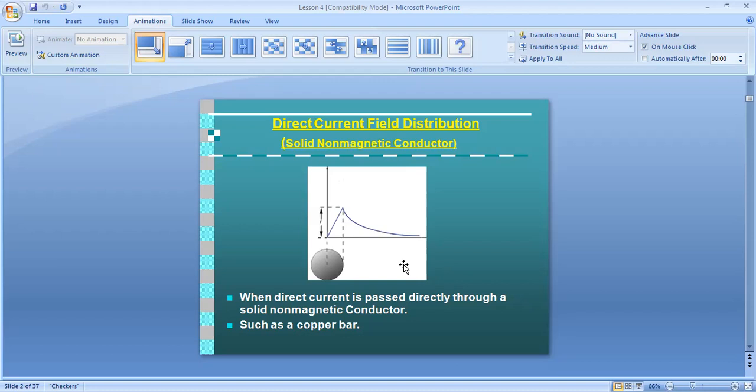That's why the field is reducing there. So the magnetic field depends upon the medium also. Here the medium is ferromagnetic material, that's why the field is high. Outside, the medium is air, and the permeability of air is very low, so you get a very weak magnetic field. That's why the magnetic field reduces here.